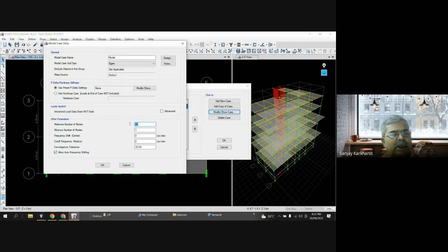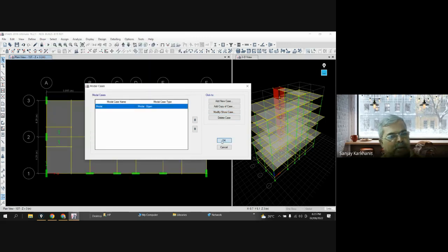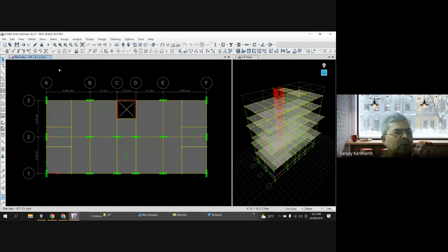Or you can check anything, you can ask it anything. The software has the capacity to carry out modal analysis up to 100 mode shapes also, right? So let's say you are not interested in 12 because you can say that sir, 5 modes are enough. So let us make it 6. You can do it. That is what you can go ahead with.